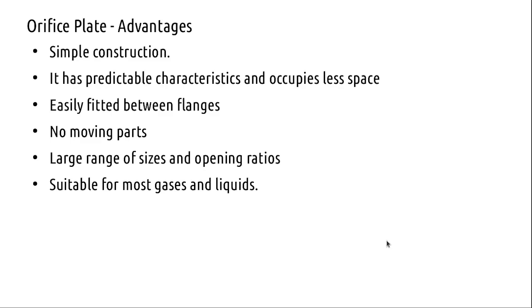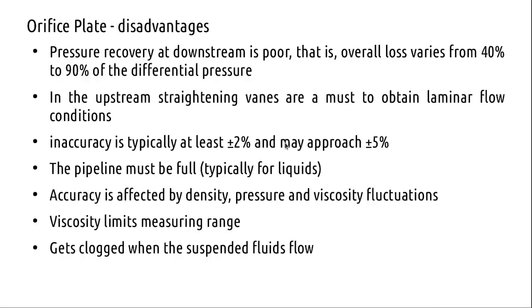Then the advantages, as we mentioned: simple construction, with no other complication. Just choose a plate of a particular diameter, put it there, you know the parameters, make a differential pressure measurement, and that's it. The disadvantages are the pressure loss, and you need to obtain laminar flow here.